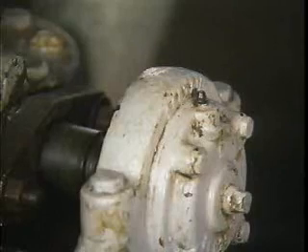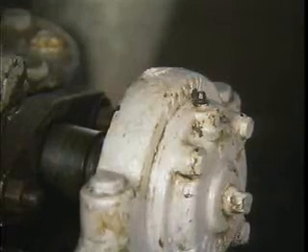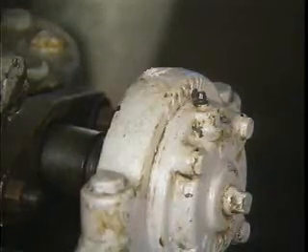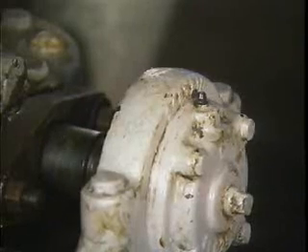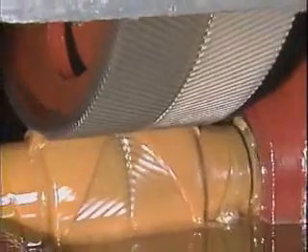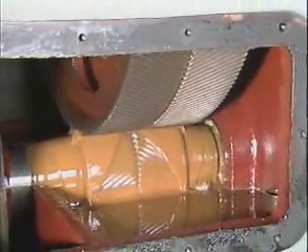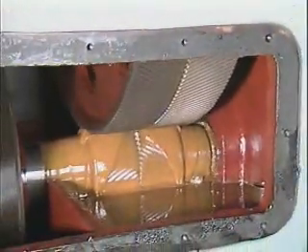Rolling friction is considerably less severe than sliding friction, but rolling contact bearings must still be properly lubricated to reduce heat and wear. Another way to reduce sliding friction is to separate two sliding surfaces with a film of lubricant. As long as the surfaces don't touch, sliding friction is eliminated.